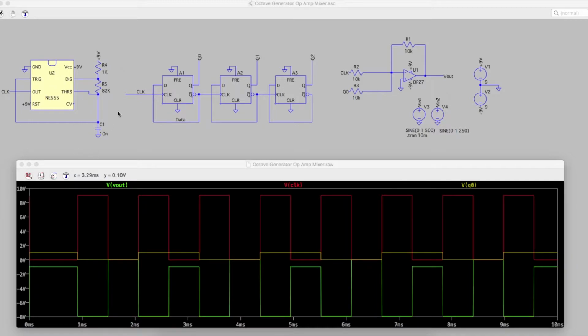So these values here that I chose for the timing on the 555 were arbitrary for the purpose of demonstrating a signal and showing it gets half the frequency at the Q0 output. And when I experiment around generating tones on the workbench, I'm just going to do whatever based on parts I have laying around, and I will eventually come and fix this diagram up to match what I've come up with.